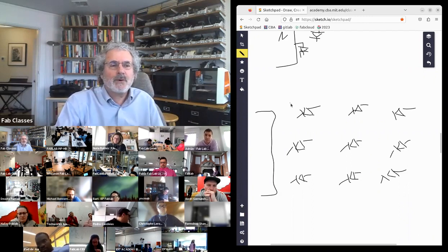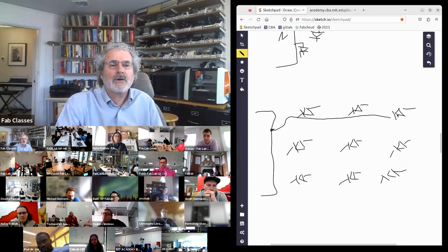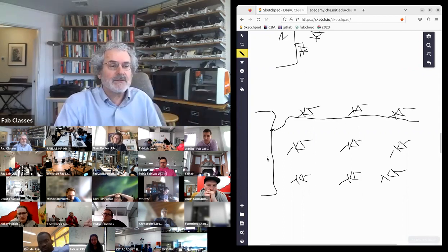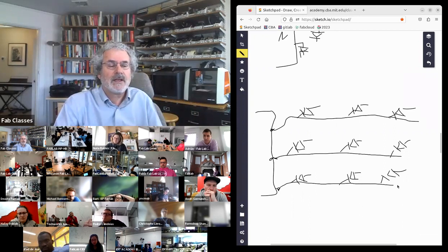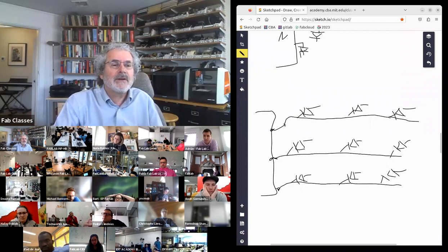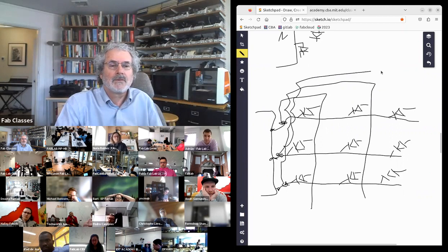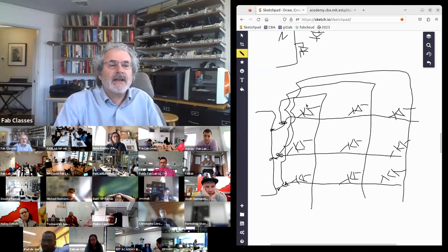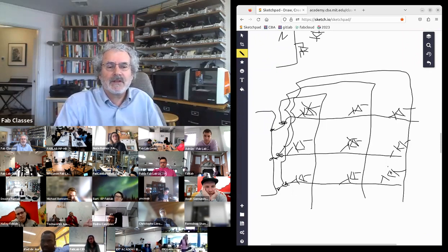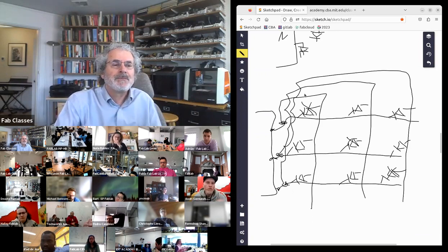Normally I'd need a wire going to each one, but here, what I'm going to do is take this pin and take it to all of the cathodes. Then I'm going to do something crazy and take the same pin and connect it to anodes. And finally, I'm going to remove the ones on the diagonal because those don't work. And so here's what's going on.